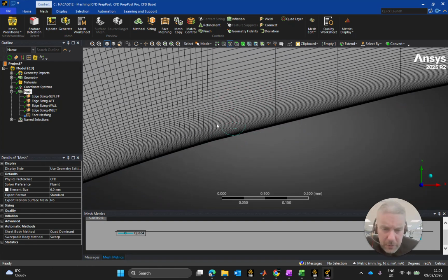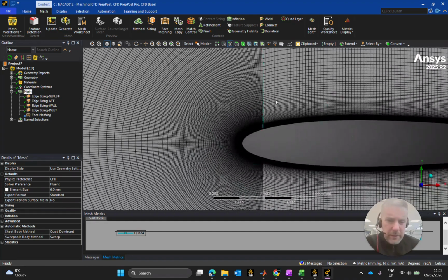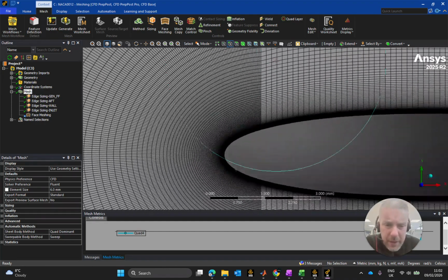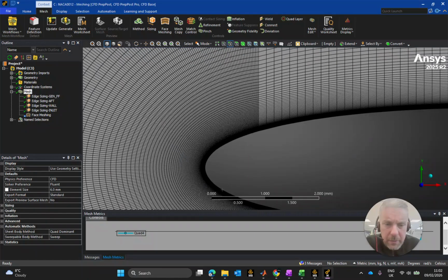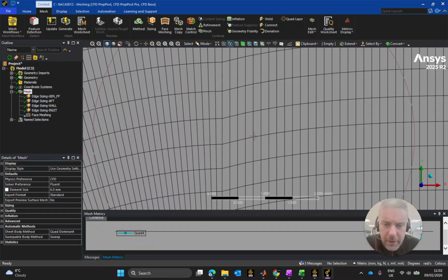However, look, there always is a wee bit of work that we can do in these. We do have a massive change in area from one section of the mesh into the other. I don't really like that, albeit it's not detrimental in this case because the skewness, the stretchiness, the difference is in the direction of the velocity along that flow, but all the same, that looks a wee bit ridiculous. I would like to tidy that up, but certainly by the time we get up here, it becomes less apparent.